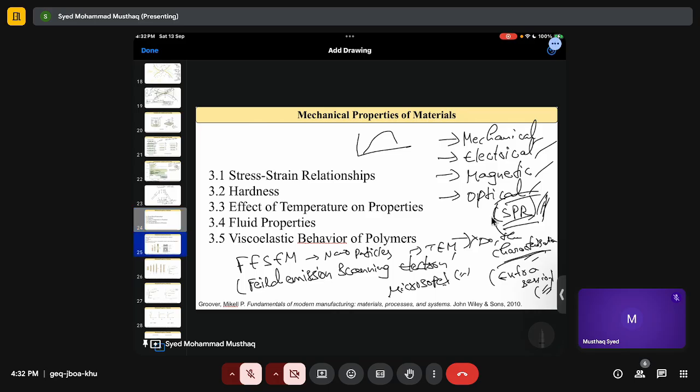So yeah, coming to the mechanical properties. If we are only touching the basics, then we will stick with only two characterization techniques. One is tensile testing, and the next one is the hardness test. These two are the most widely used testing techniques to measure the properties of a material. From hardness testing, you will get the hardness value of the material. That is one point. And from tensile testing, you can get many things: yield strength, elastic modulus, the deformation flow curve, constant terms, and many more.